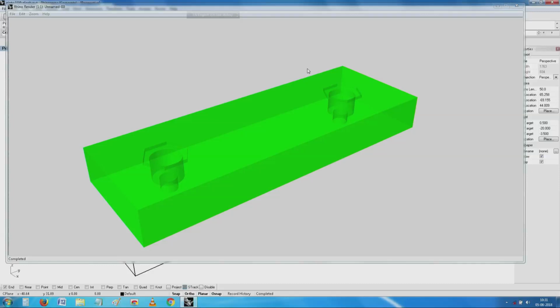What we have there is, just for the purposes of illustration, a solid in which there is a provision for putting a threaded insert. In all other places, say if it were aluminum and very small, we put a riveting nut or something. If it is sheet metal, on one side we have a riveted nut, or if it is a casting, we use something called a helicoil insert.